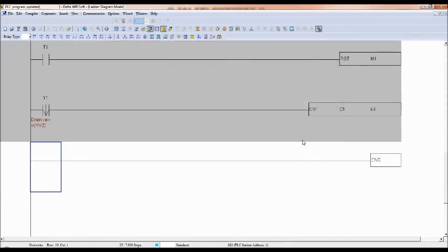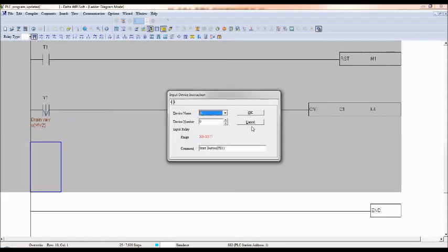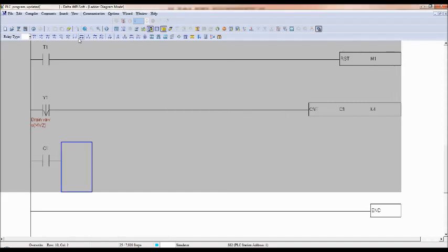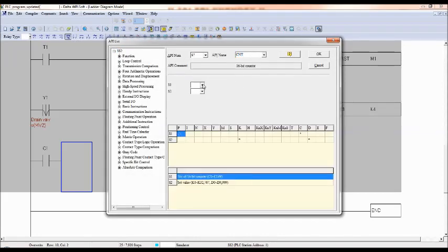So I'm using the input to the counter as Y1. Okay. And when C1 is on, what is our requirement? The buzzer should be on, right. The buzzer should be on and the end indicator should be on. And the cycle should not be started. So for that, when the counter C1 is on, we can use a reset function. This is a reset function.